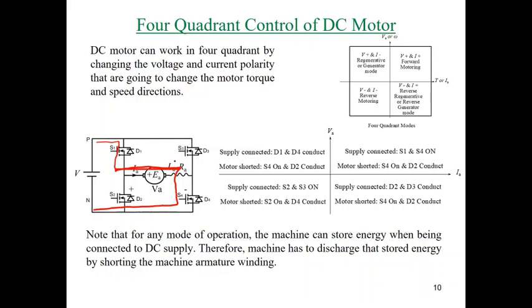So we need to control the voltage, for example, reduce this voltage. So what we can do is control the voltage magnitude. How can we control the voltage? Simply by turning the switches on and off. If we disconnect switch S1, what will happen, Shabab? For the first case, when the current has flowed in this direction, there is stored energy now in the machine. If you disconnect switch S1 and you have stored energy, what will happen?